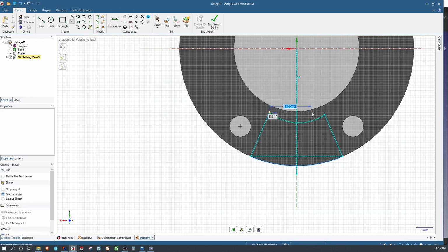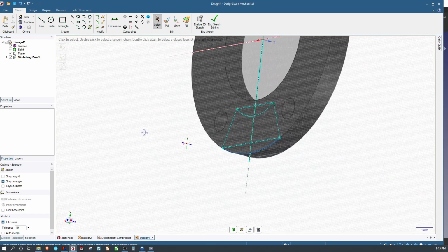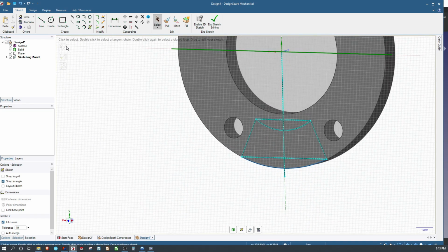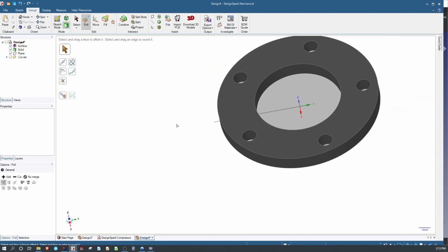Construction line again. We'll set our construction line to be horizontal. That's not fully defined, but I think that's going to meet my needs. It's a direct editor, so I'm going to give myself an excuse to not fully define.